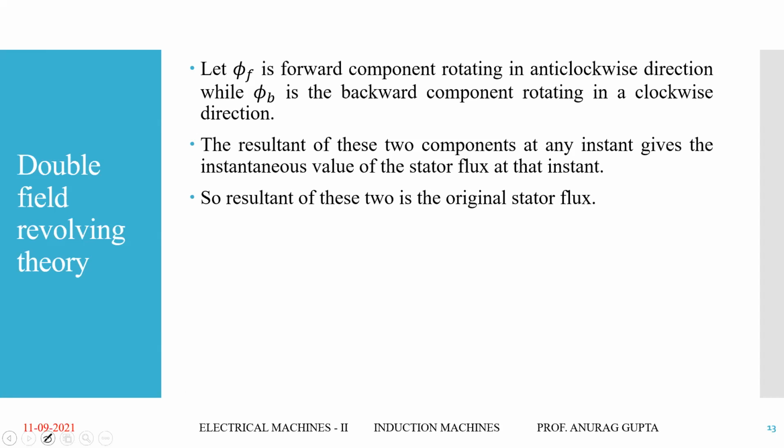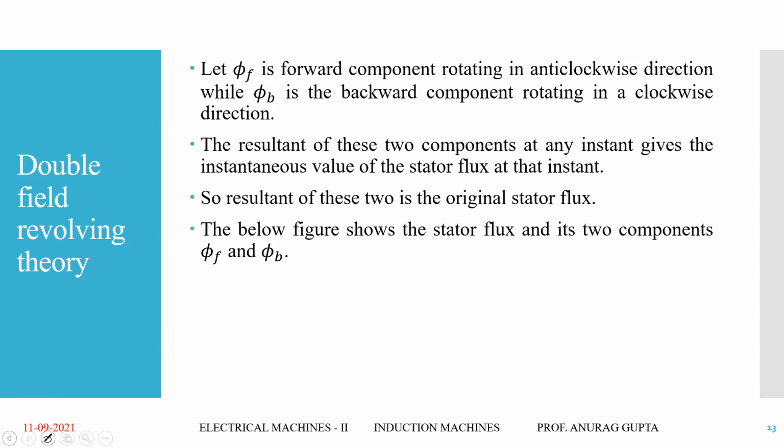Induction motor is an AC motor, and everything is alternating in nature, so whenever we talk about the summation of any alternating quantity, it is only a vector sum. Never do an arithmetic sum for any alternating quantity directly.